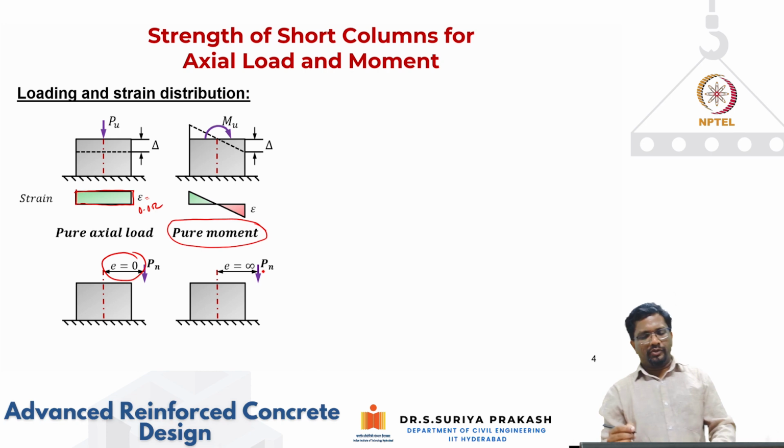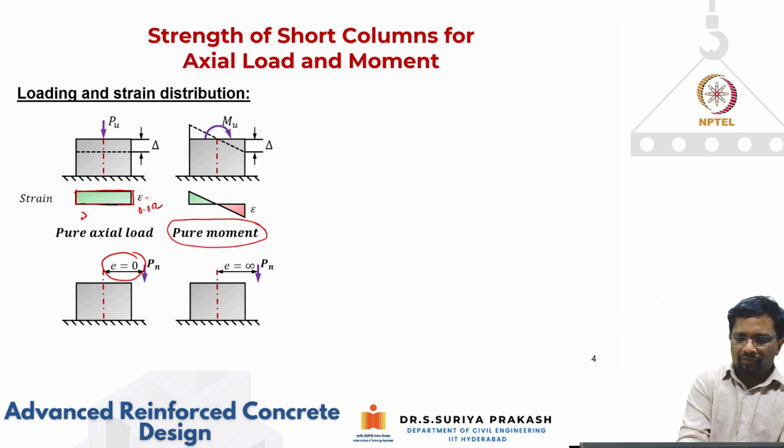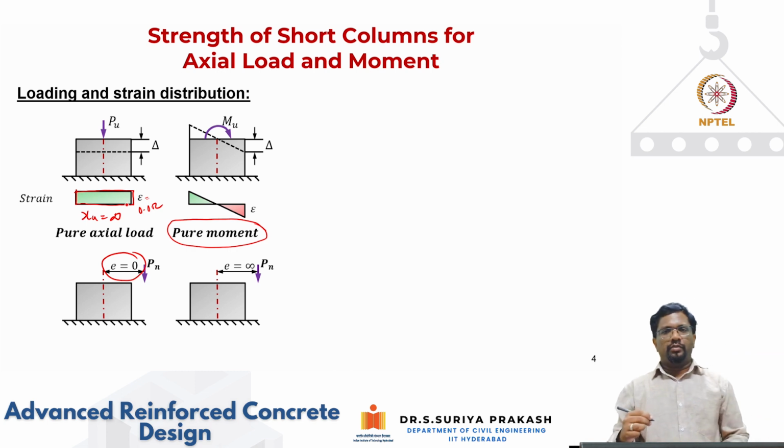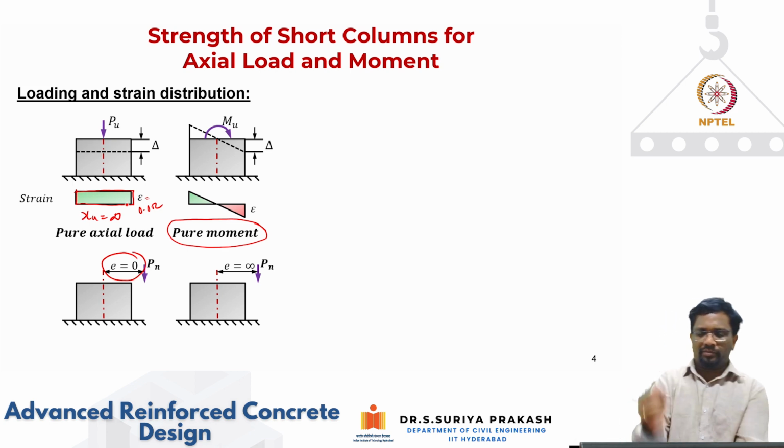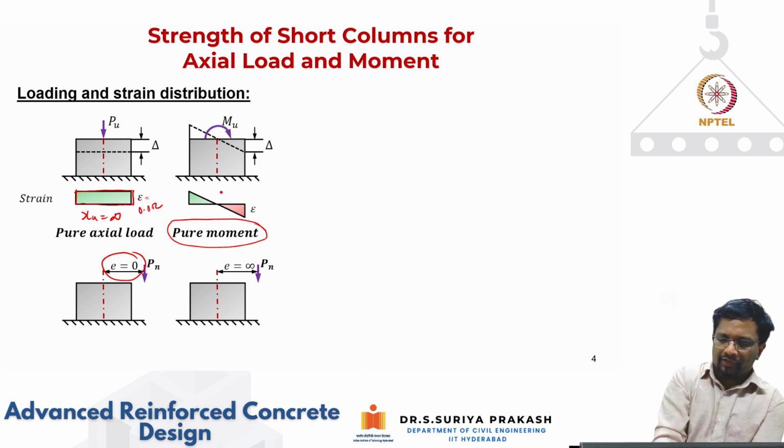And you should also know that in this case the neutral axis depth is going to be infinity, right? Because it's under pure compression, you will not have any bending. So when you have no bending, your neutral axis depth will be at infinity. Here xu will actually be minimum. Okay, so there are two extreme cases.